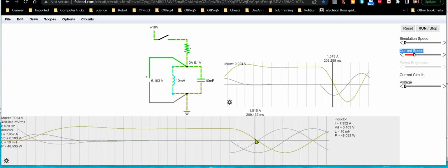Remember, it's fighting for its life here, but now it's dead. It's got zero energy in it, and the capacitor has all that energy in it. The inductor's not generating any voltage anymore. It's fully out of energy, and it will generate voltage right up until it hits zero on the current. At that point, that voltage field will disappear. If we took the capacitor out of this situation, you would see 0 volts on this circuit, just like we had earlier, except there's no current in the inductor anymore, so the system would be flatlined.